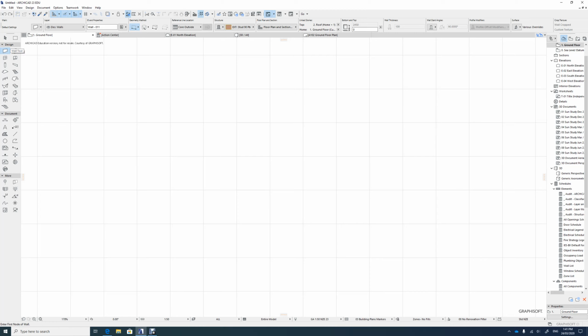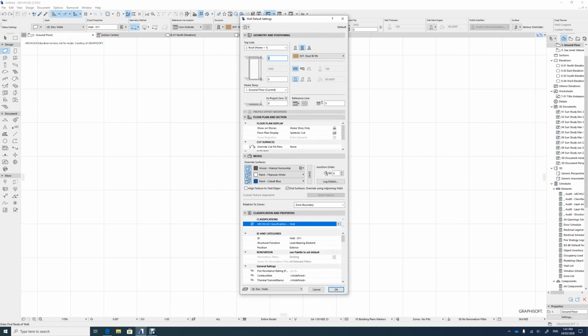So when you're doing your walls up here, double click into wall. You guys are going to create quite different looking tiny houses. So you want to unclick this from the roof. Go not linked, because you're going to need to change that height of your tiny house. If you're 2-story, remember that's going to be 4.2 metres, which is 4,200. So that's going to be the full height of both of your walls.